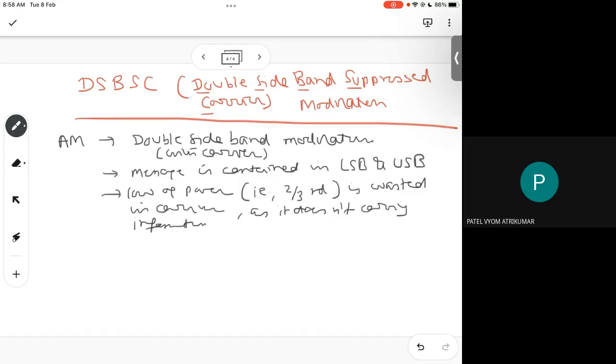So basically, in the AM modulation, which I have written in the first slide, there are three expressions: one corresponding to the carrier, another fc minus fm, another fc plus fm. The two side frequencies contain the complete information, and the carrier power is more than the side power, which is a wastage.